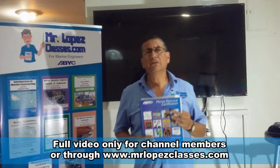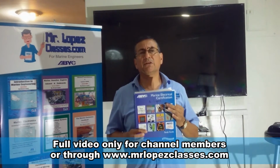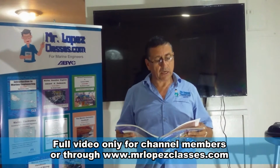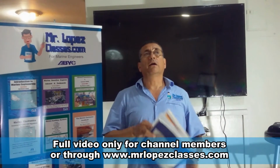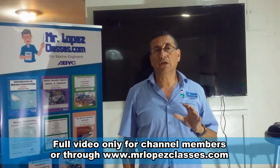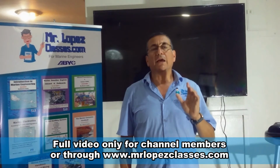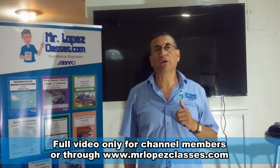A couple of additional things related with the ABYC study guide specific for chapter 6, inverters. In the ABYC study guide chapter 6, there are important recommendations that I want you to read carefully. For example, one of the recommendations is in relation to the capacity of the inverter according with the capacity of the battery bank. The capacity of the battery bank for any type of marine inverter should be no less than 800 CCA. 800 CCA is the minimum according with ABYC.